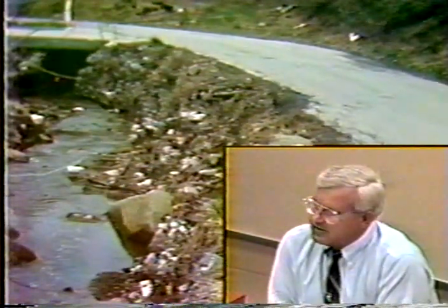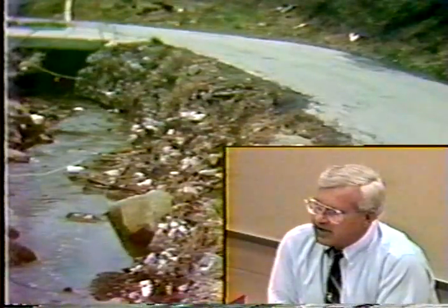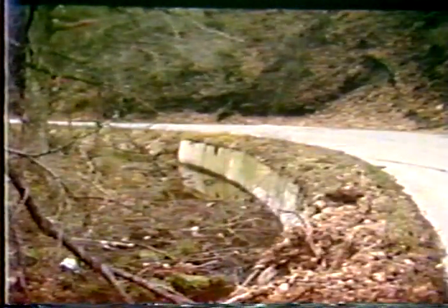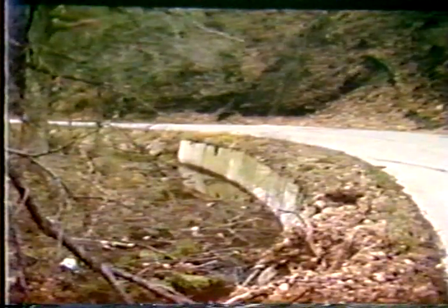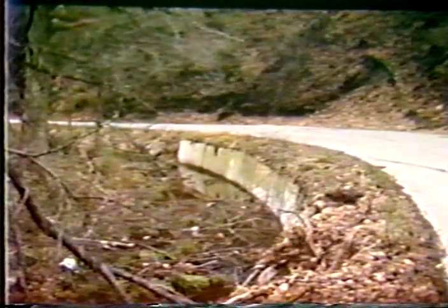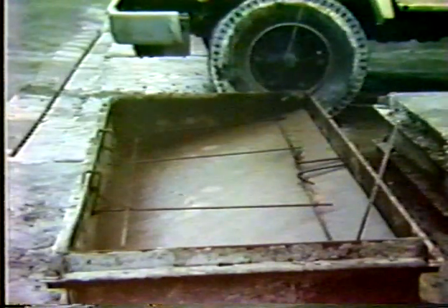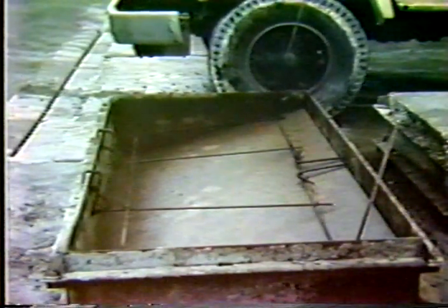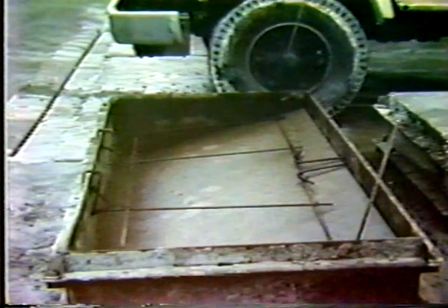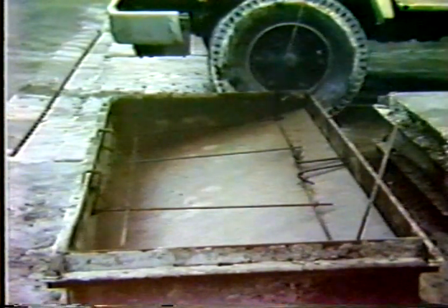He surveyed his problems, I think, and realized, how am I going to fix this? Well, he used a concrete barrier wall, or a portable wall, actually. And this is a very nice scheme of what he did. He got with a local concrete company, and they made a special form to make a concrete wall. But it's a portable unit. What you're looking at there is after they cast the concrete. As I showed in the previous slide, he uses a little reinforcing steel in there. And he stockpiles these small walls in the concrete yard and goes and gets them when he needs them.